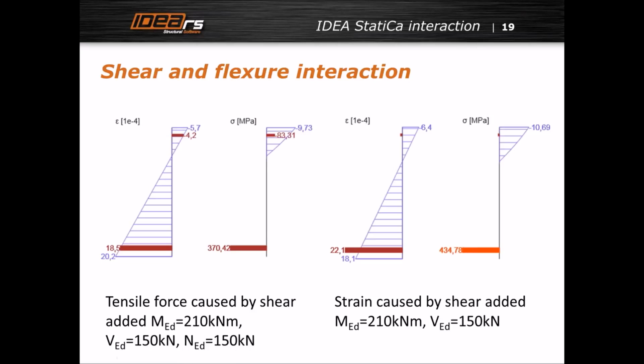So we evaluated the normal force going to longitudinal reinforcement and it is induced by shear. We applied it, and in that case the whole section resisted. That's why we didn't even get to the plastic branch here in the tensile reinforcement, and we decreased the compression in concrete, which we actually didn't want, because we didn't want to use the compression reserve of the compression zone.